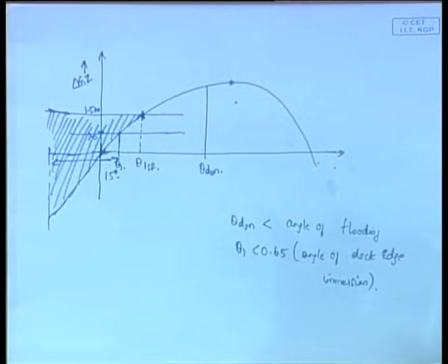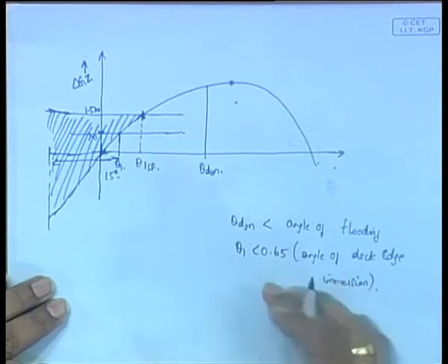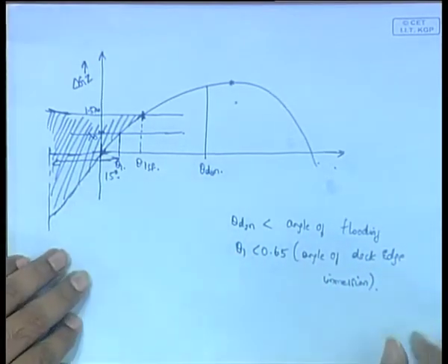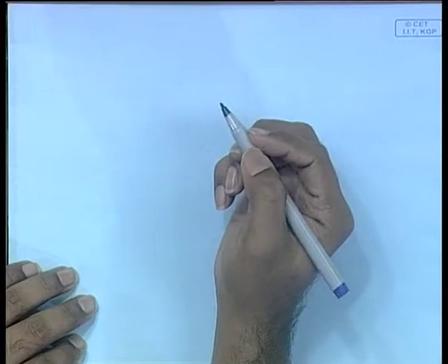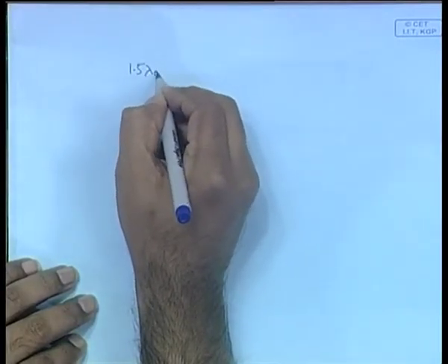Okay. So these are your two conditions which should be satisfied by the ship finally. This is what we are going to check finally. If it satisfies both of these, we say that it has passed the test. Okay, now let us do that problem. So this is what we are going to do. First we calculate the wind lever, we have calculated. Then you calculate lambda 0, which we have done, then we do 1.5 lambda 0.